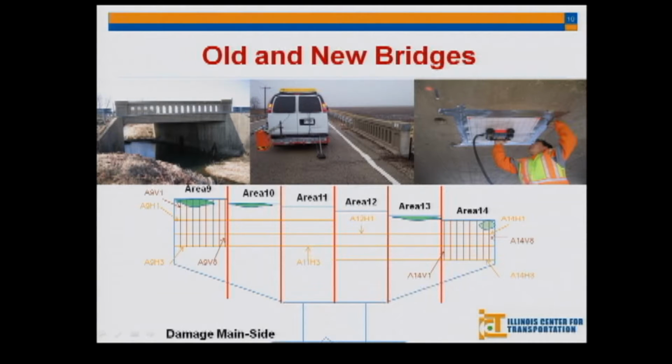Actually, we used an impact echo along with that as a verification too. So we were able to know where the distress is and identify it for the agency in order to find out if this is solid and they can use it or not. So we found that it was safe, and the project was completed. If they weren't sure, that could have been a lot of money because they would have had to take the whole system out.